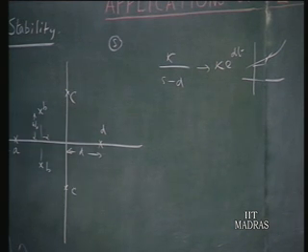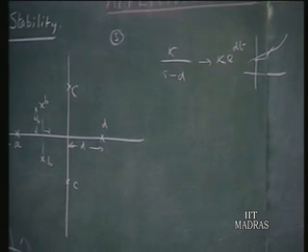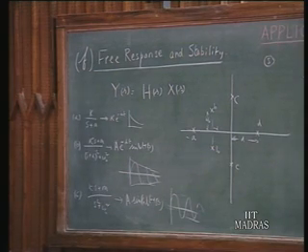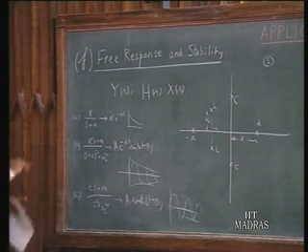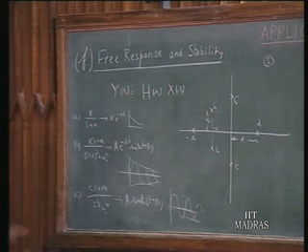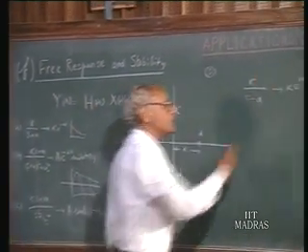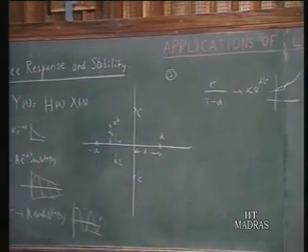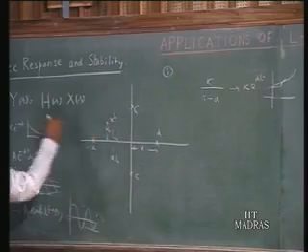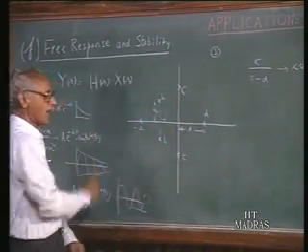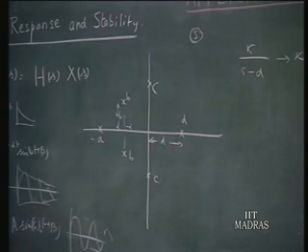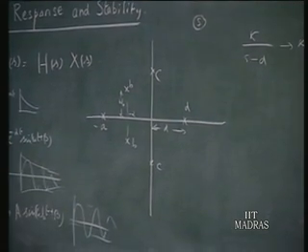So one can say that if the system is stable, if you give a bounded input giving rise to an X(s) which is finite, then the natural response must decay with time, or at least stay steady with time. It should not take off, it cannot go indefinitely to large quantities. Therefore, for a stable system we require all the poles of H(s) to be in the left half plane, and as a borderline they can be on the imaginary axis, because that is the limiting behavior.